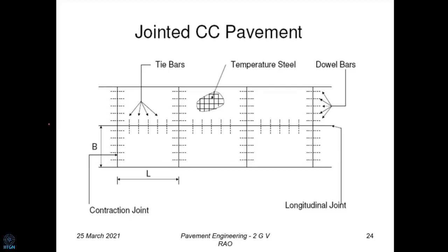Okay, so it's not something specific. It depends upon many things actually. And as I told you, the placement of dowel bars is also going to depend upon how the load is transferred, where the maximum stress is going to come: the wheel load stresses, the temperatures. Temperatures can be due to uniform expansion and contraction and also due to difference in temperature. That's a very interesting topic by itself. We can deal with it if you give me time.